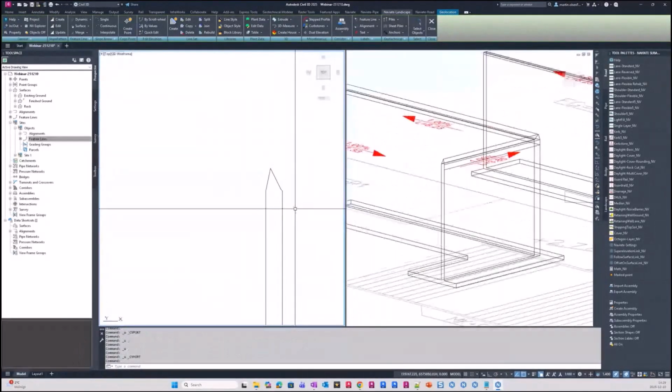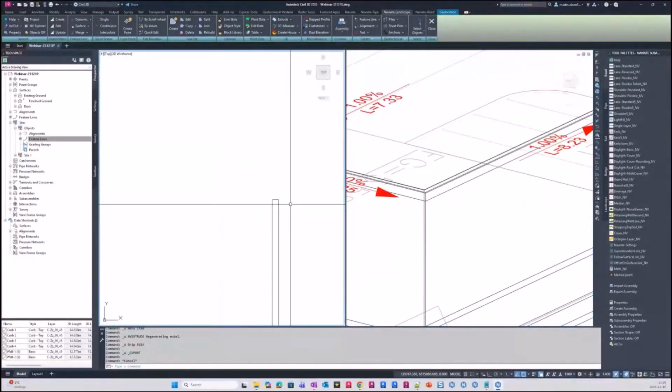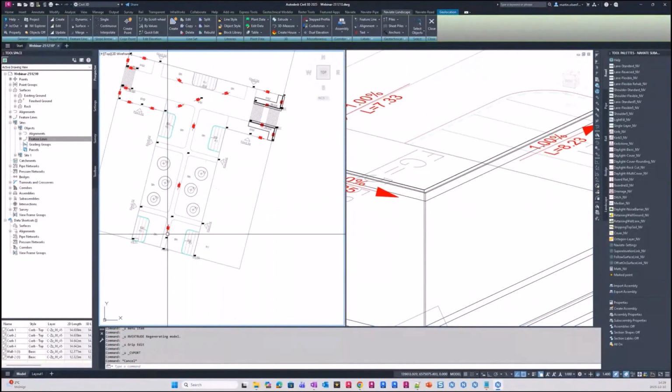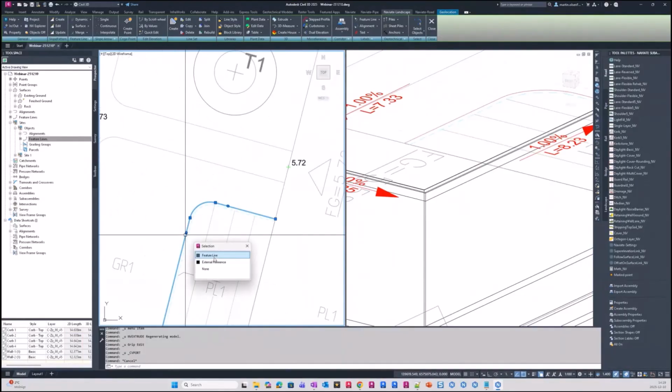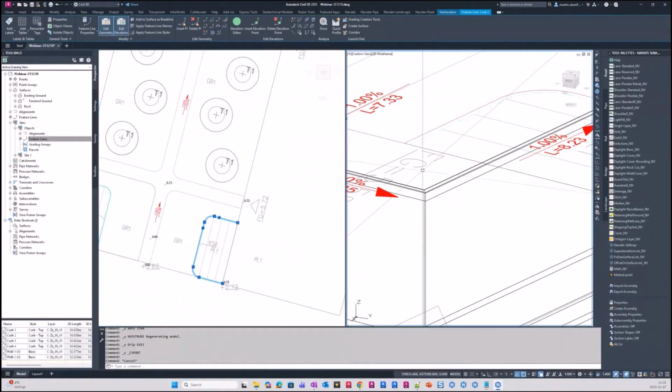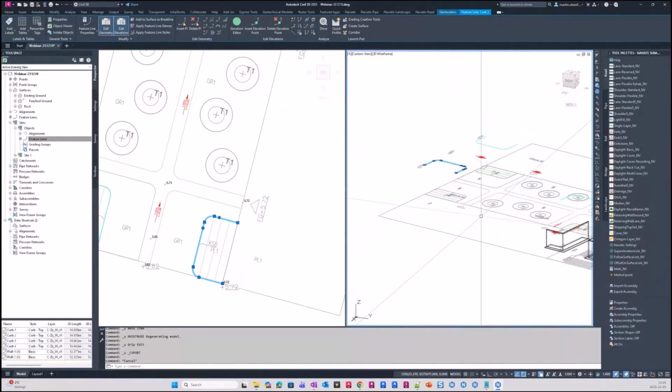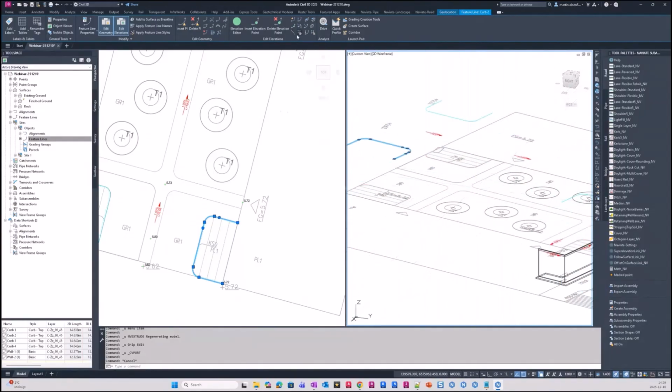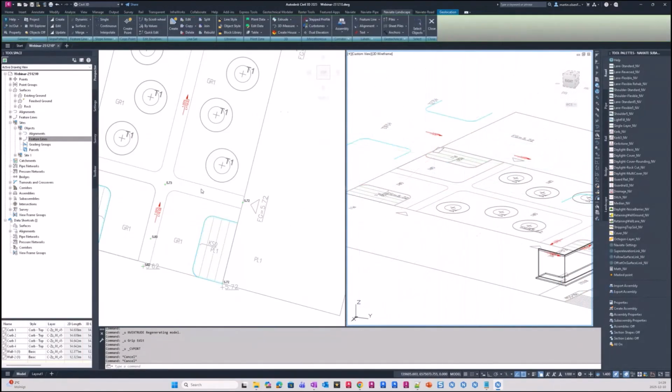It's also possible to do this extrusion by script. So if you got, like in this case, I got some feature lines that is attached to the surface. I use the feature elevation from surface to get the heights for these feature lines. Use this function, pure Civil function. And then now I will run a script for doing this extrusion instead of picking each line. And this can be good if you're working with a lot of lines that you want to have 3D objects from.